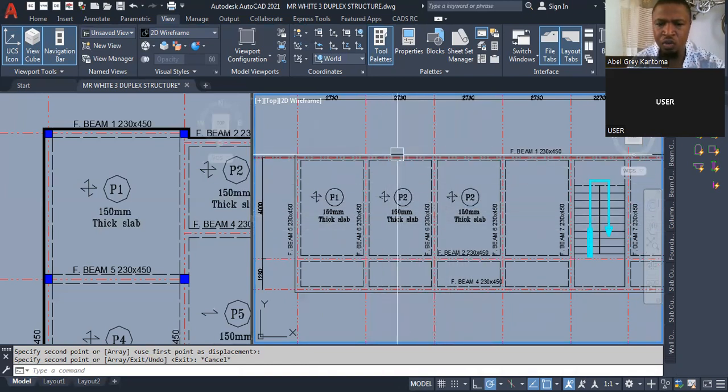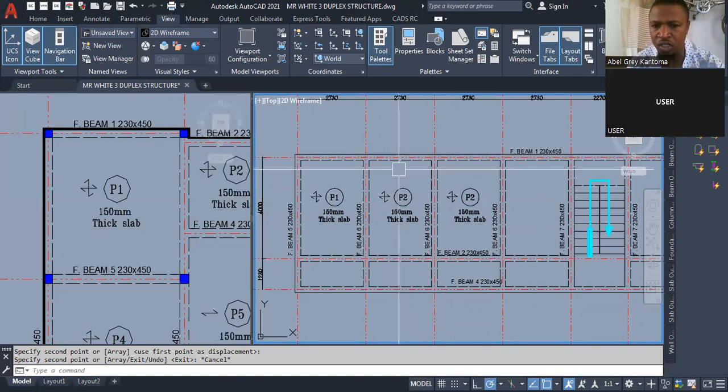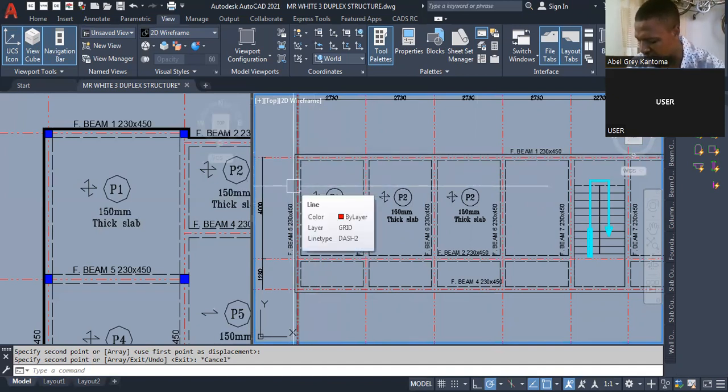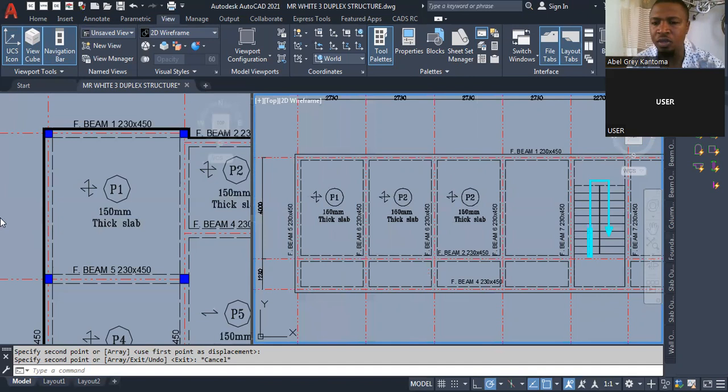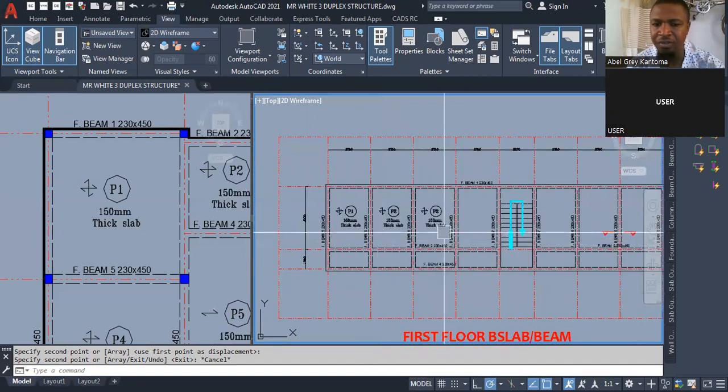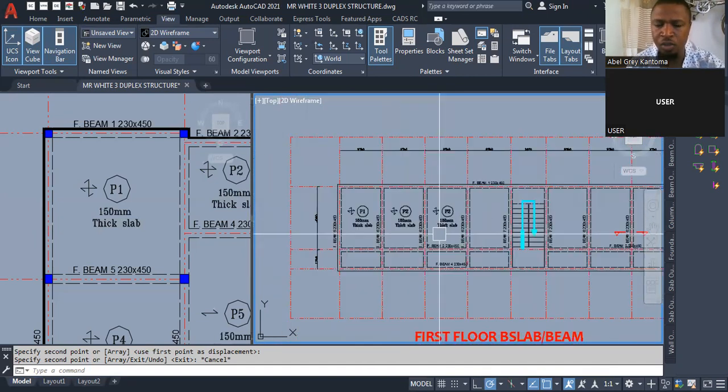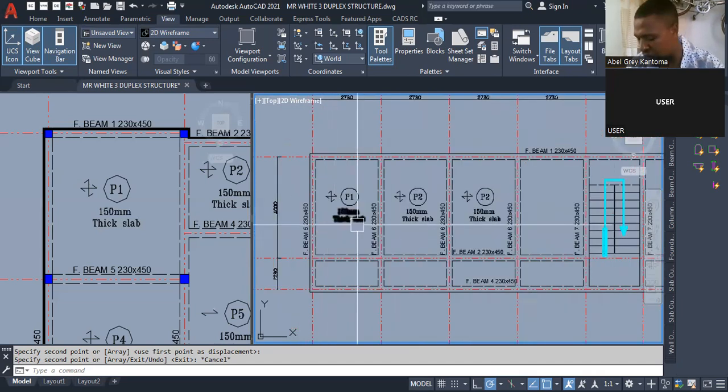You can see you have the short edge that is discontinuous. You have 3 edges that are continuous. But in this case, you see this panel, even though they have the same shape with this one, it's different in that you have 2 adjacent edges that are discontinuous. This is actually a bit deep. You need to understand that part. I have talked about it very much well, most especially in my training on RCD 2000.